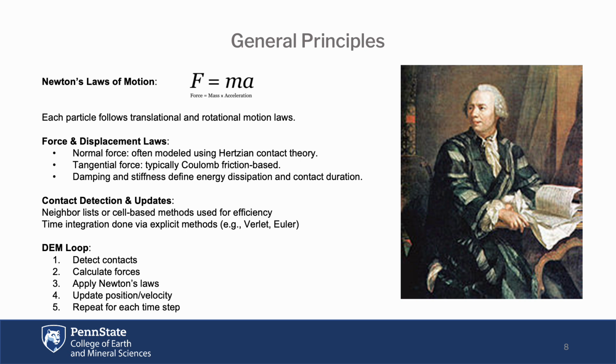The core principle behind the discrete element method is the application of Newton's laws of motion, both translational and rotational, to each individual particle in the system. This means DEM tracks not just the position and velocity, but also angular motion and torque for every particle. To determine how particles interact, DEM uses force-displacement models.